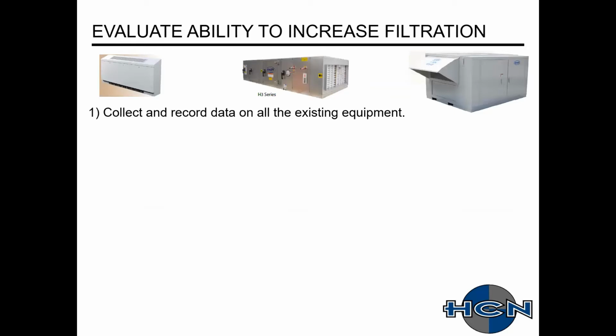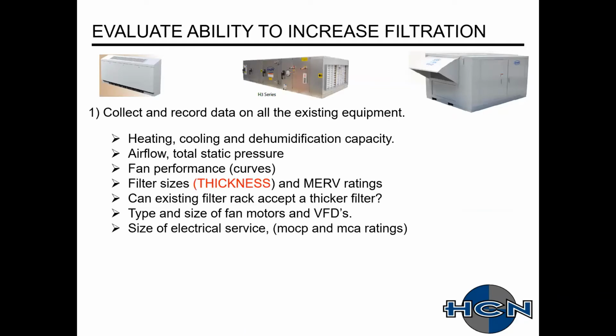All right. So what the standard, and I'm paraphrasing, trying to summarize what the standard is saying, is that they want you to collect and record data on all the existing equipment. What that encompasses is you should look at your heating, cooling, and dehumidification capacity, your airflow, your total static pressure, your fan performance.